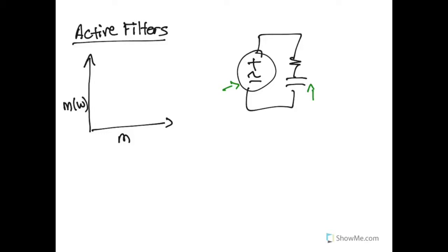And so what this means for a particular filter is that if you look at its transfer function, the maximum value that's ever going to be up here is going to be 1. So at best, you're only ever going to get out what you put into the circuit. So if I'm sending in a 5-volt signal and none of it is getting filtered, I'm probably going to get a 5-volt signal out. But once my filter begins to operate, that value might change to 2, 3, 4 volts, depending on the amount of filtering. What these basic RC and RLC filters cannot do is provide amplification for signals.